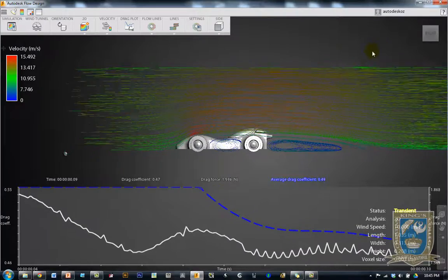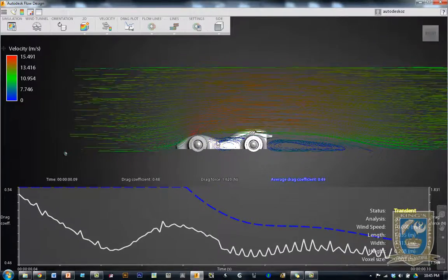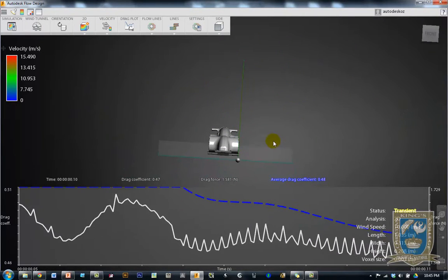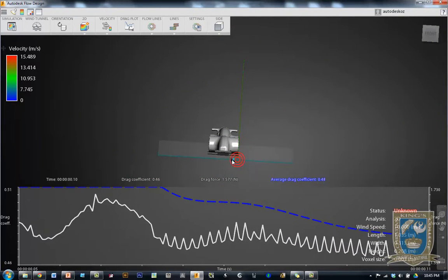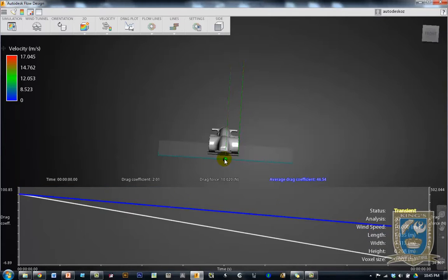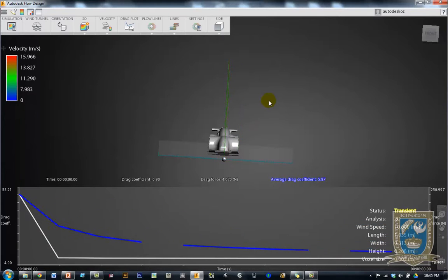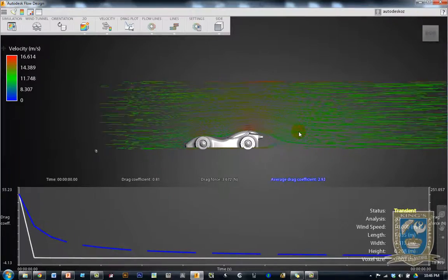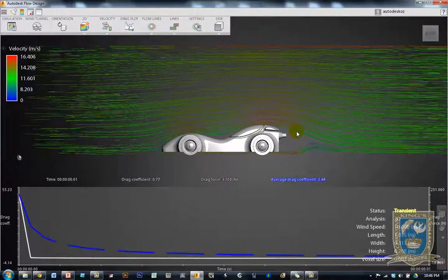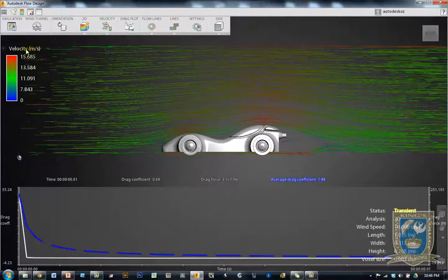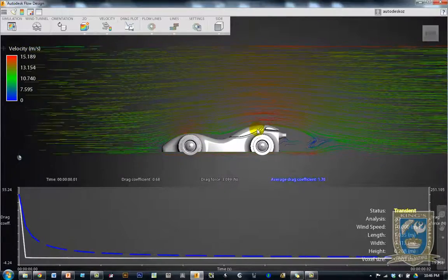So what I want you to do is use your left mouse button. Drag around, and drag the little ball right into the middle position. Let the curtain readjust, just move it slowly, so you're pretty much dead smack in the middle of the vehicle. Click the little house to take you back to straight. Use your mouse wheel to scroll in. Bring the vehicle up so you've probably got the green screen level with your vertical in this area, car in the middle.